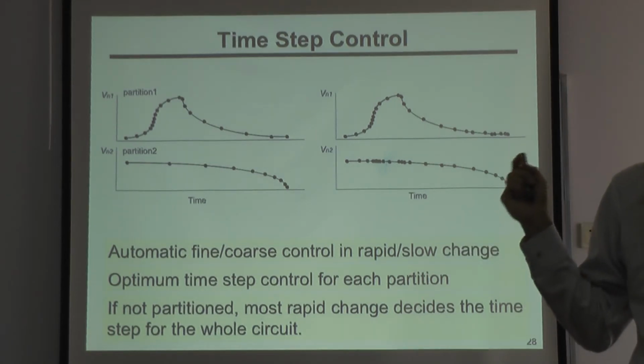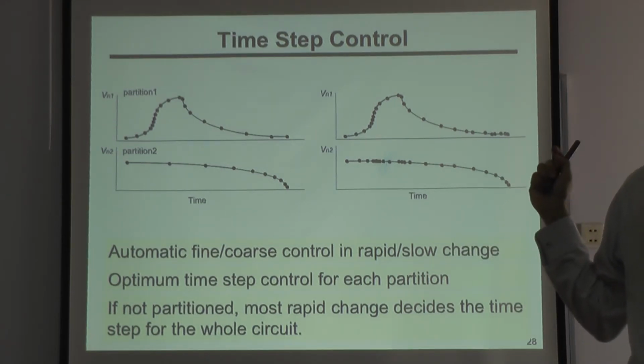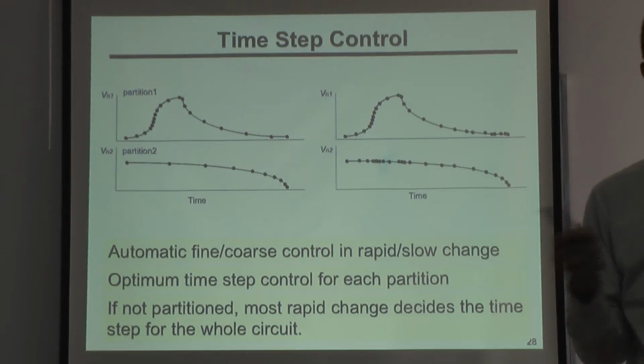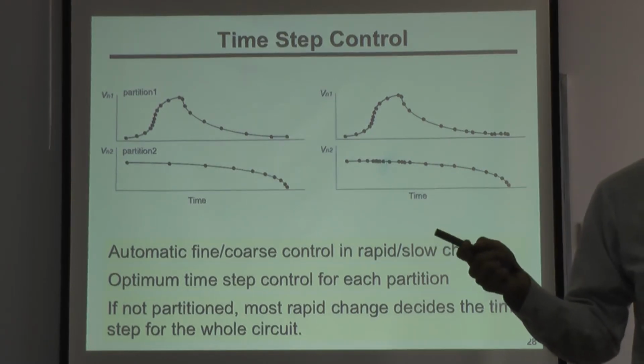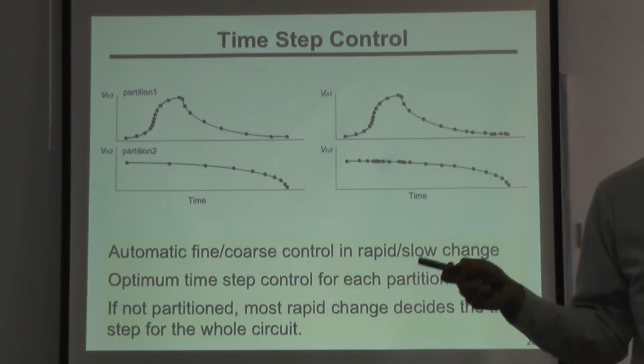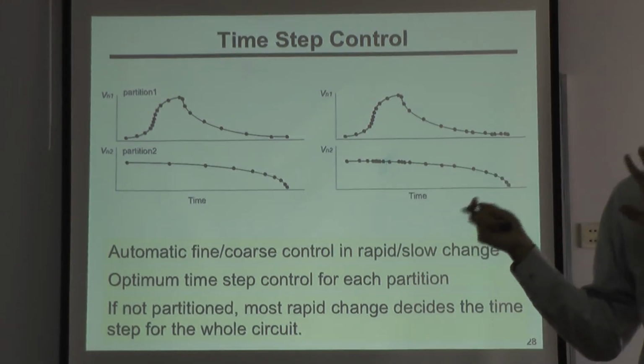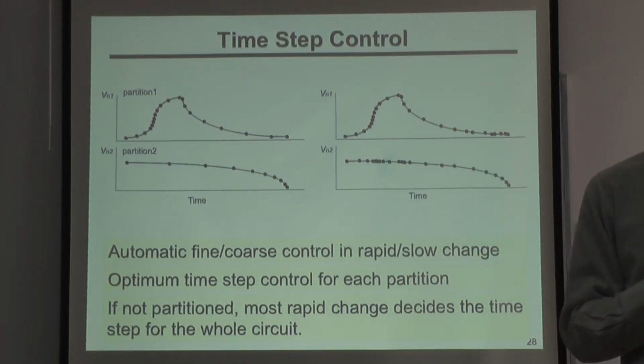It also automatically analyzes which is an analog block that should not be partitioned or should have more accurate results, versus the digital part which can be partitioned more aggressively. It automatically considers that, so we don't have to worry about it.